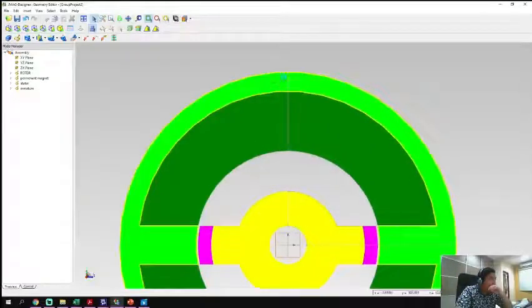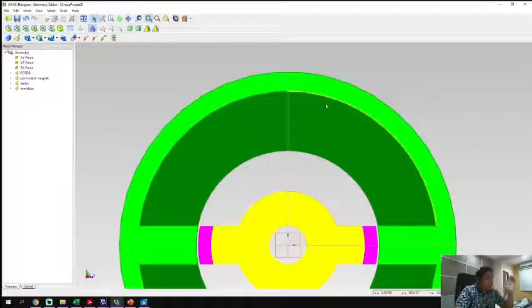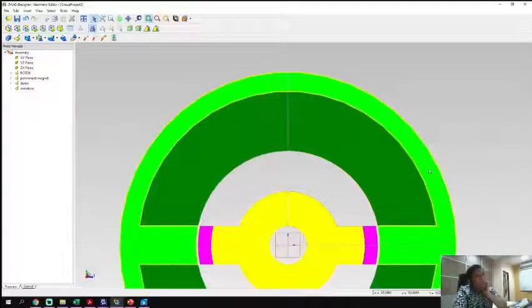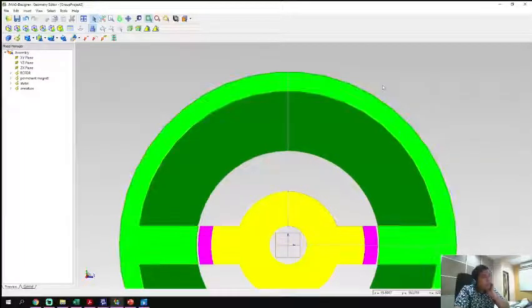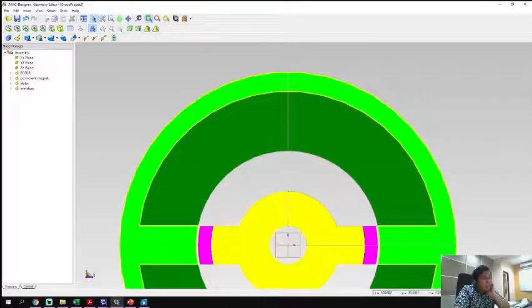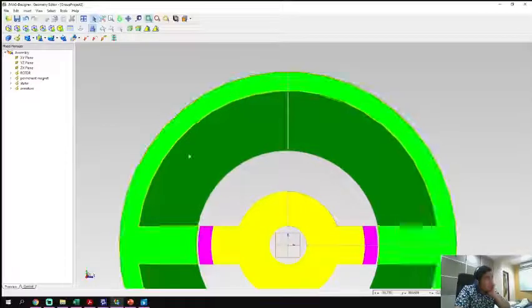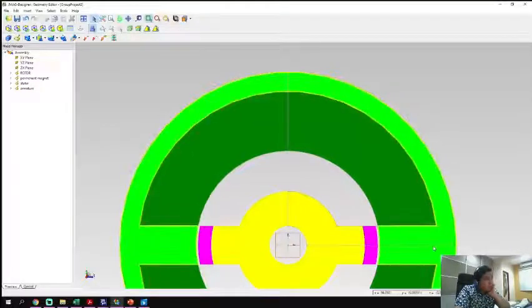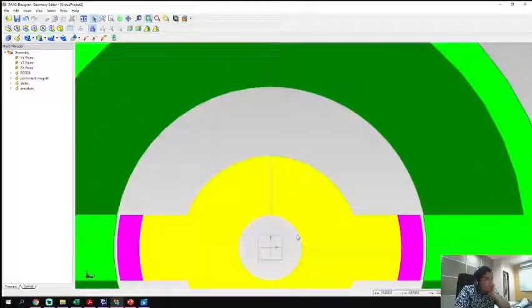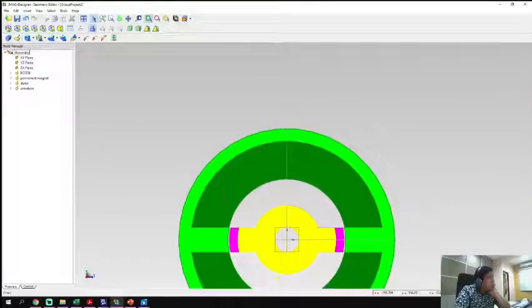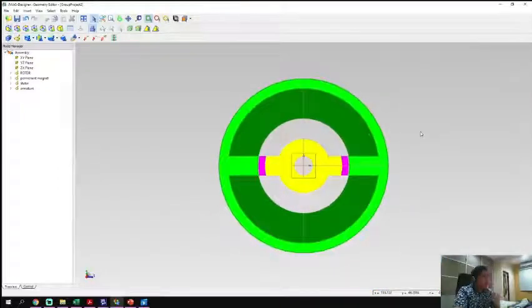As you can see, we have created a line here, so we can mirror it. Before that, we make a region first, the L shape. We create a region, and then we mirror it to the left side, and then we mirror it to the downside, so we get the full circle. And then we make an armature coil. As you can see here, they have 4 parts.